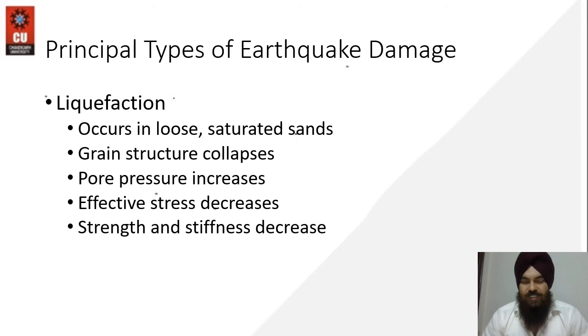So for a very small period of time, that soil mass or subsoil is converted into a liquid or fluid. The shear strength of the soil beneath the structure becomes very small or nearly equal to zero because of the increase in pore pressure. That leads to a decrease in effective stress, and further the strength and stiffness decrease.